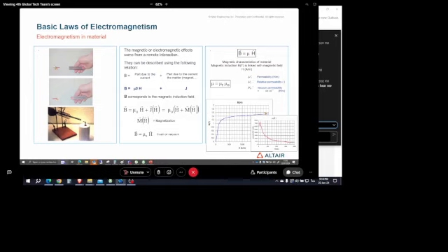this material. What does it mean? If we plot the relative permeability, we can see that it starts with very big values, and then the more magnetic field you put on it, the more this mu r tends to 1 actually. And when mu r tends to 1, the material will behave as air or vacuum.